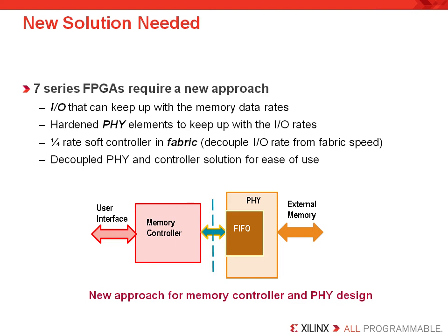The I/O interfaces in the 7 series are high performance. This is especially true if you increase the auxiliary voltage domain, which is used to power the I/O pins, and thus increases the I/O performance. The problem is that the DQ and DQS signals of the interface will require some special logic.